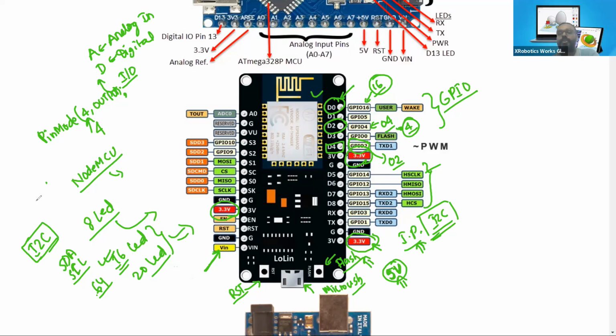When you use more than one servo motor along with the microcontroller, you will see power surges or difficulties. Many teachers and many people will only show you the positive part, but no one will show you the negative part of using all this stuff, right? The negative part is that when we overload our board in terms of power consumption, the board will start rebooting again and again, meaning it will automatically switch off and on again and again. And at that time you will be dumbfounded, trying to understand what is happening with your board.